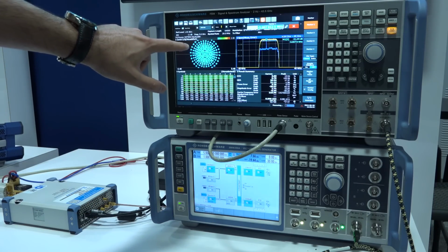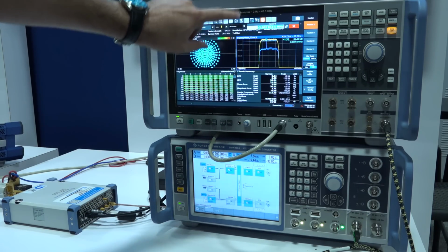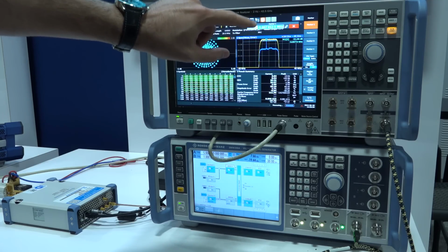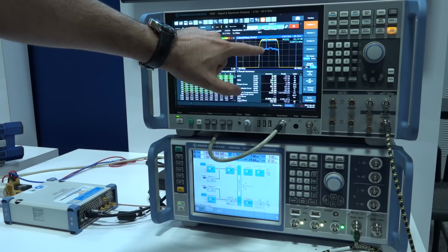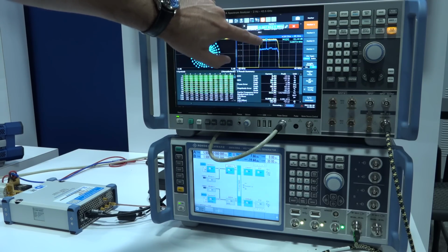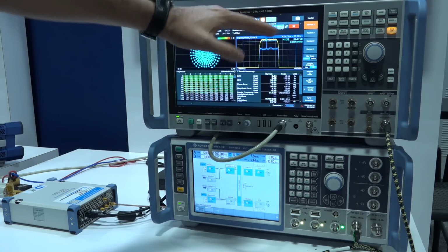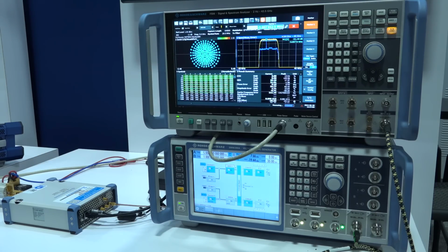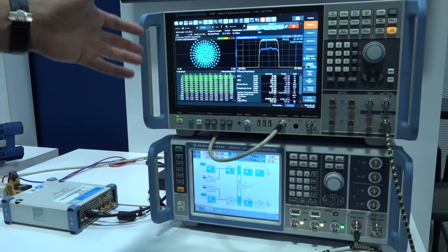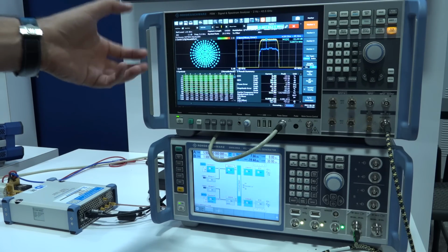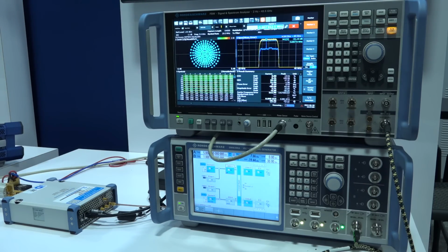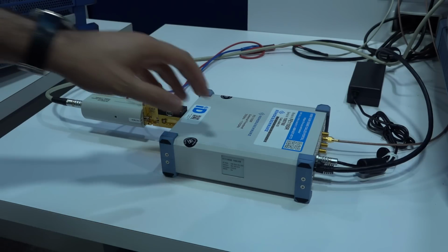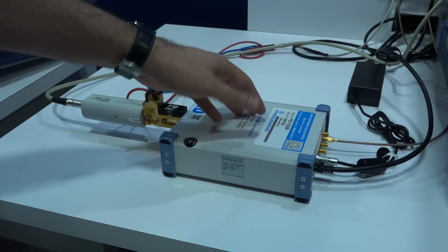and you can see the constellation degrades. But what it does is that it simultaneously de-embeds the error of the constellation directly on the spectrum. So you can here see that there's two different kinds of interference sitting on top of each other, one of them being a strong tone present, and the other one just raising a noise floor, and that's what's causing the EVM to go down. This is extremely helpful to debug what is going on in your system, whether the noise is coming from your circuit or is coming from an interference. A pretty powerful combination.